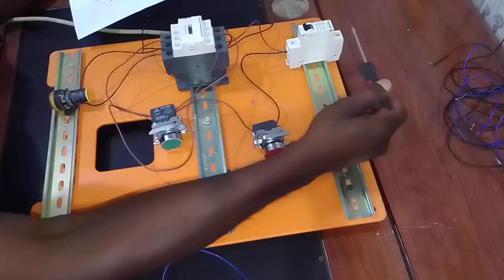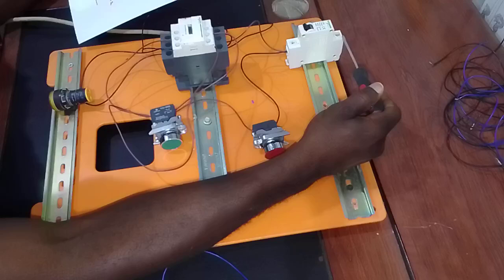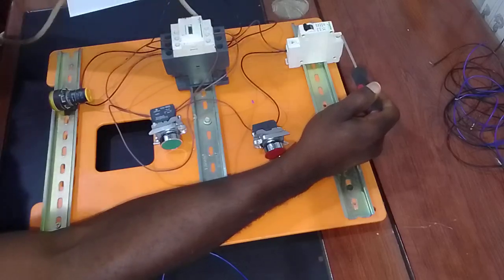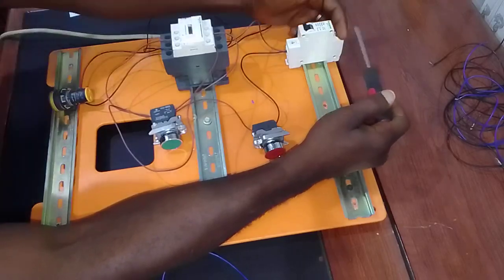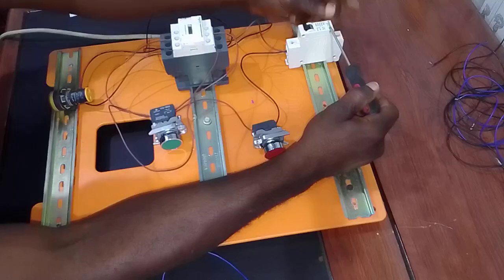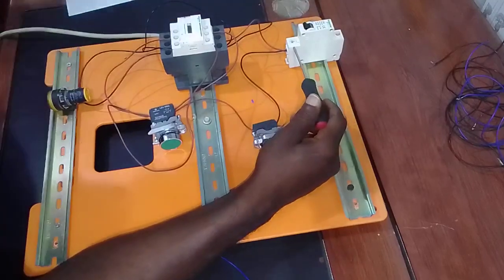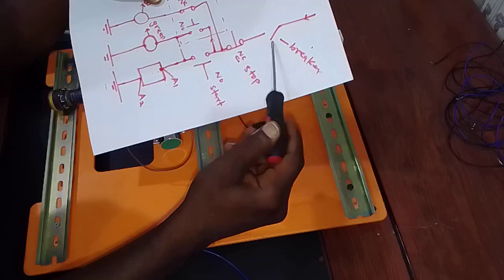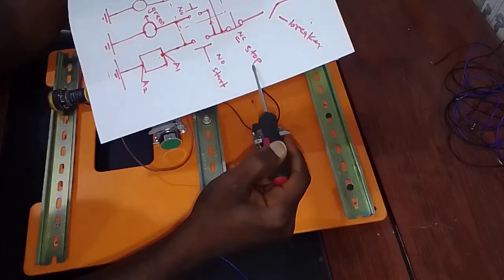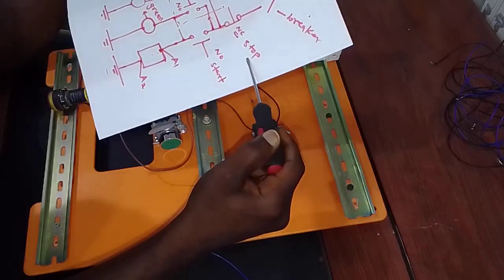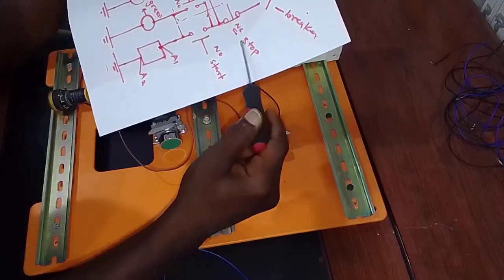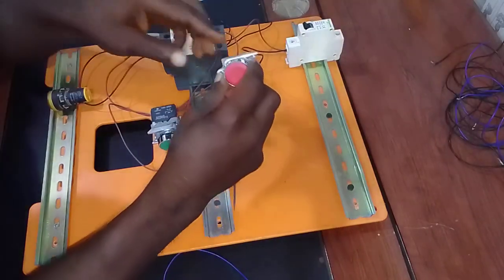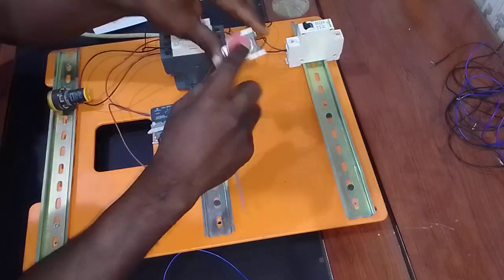From the circuit breaker, the input is connected to the live conductor. We have a power supply here, the live and the neutral. The live is connected to this circuit breaker. And the output of the circuit breaker, like you see here, one of the outputs from the circuit breaker is connected to the normally closed contact, which is the stop push button. Our stop push button is normally closed. This is our stop push button.